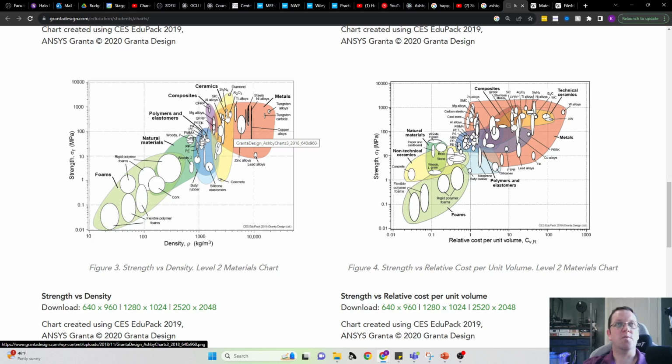Silicon carbide, really tough stuff. Silicon nitride, so nitride coated things. Titanium nitrides are way up here in these ranges. So a lot of different nitride ceramics are very, very tough. So glass is going to be somewhere down in the lower regions. Polyethylene, polypropylene, very common for water bottles and things of that nature. So reasonably strong, proportional almost to a lot of kind of woods, not necessarily for all the polyethylenes, but a lot of polypropylenes are a little bit stronger.